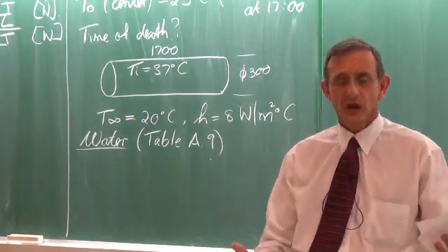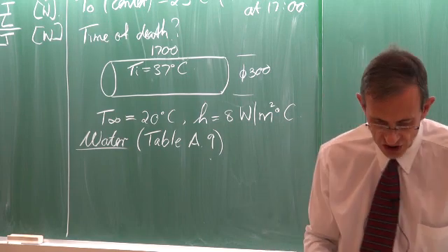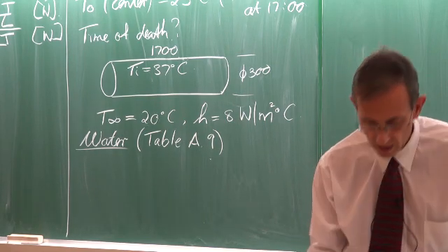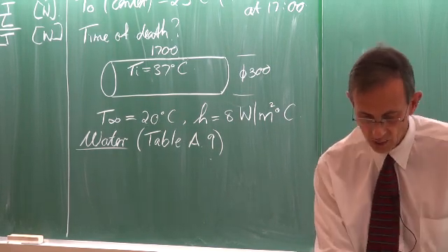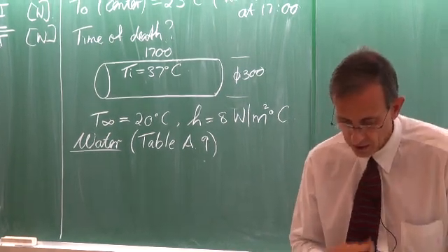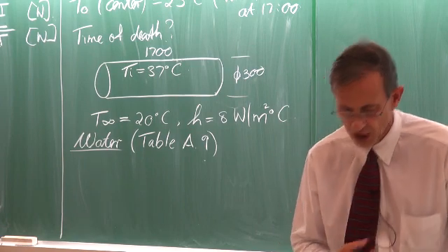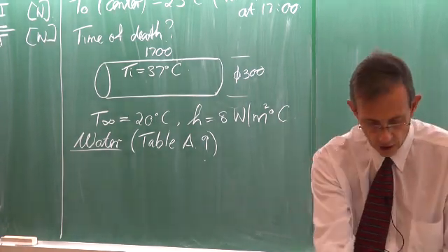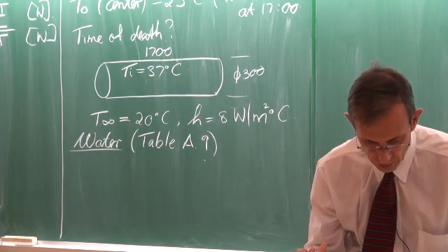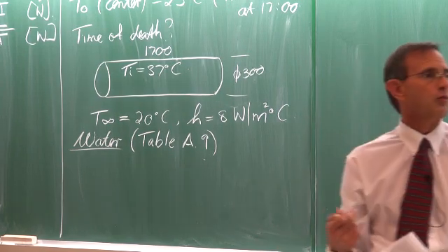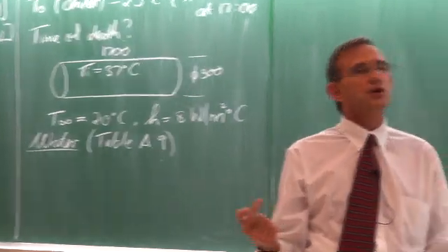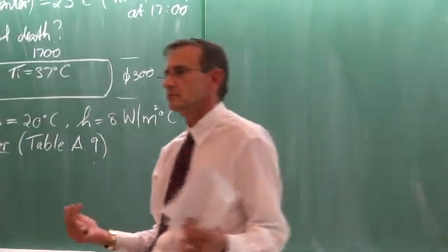Now, if you look at this table, you'll see that the pressure is given, density is given for a liquid and a vapor, then the enthalpy values, specific heat values, liquid and a vapor, thermal conductivity, that is what we want, viscosity values, Prandtl numbers, and the volume expansion coefficient. But they are all given as a function of temperature, from 0.01 to a temperature of 374.14. So, at what temperature would you suggest we use?